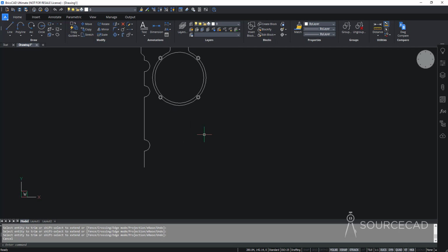So once again, I'll start with a construction line, and I'll go to the line tool and I'll maybe select this center. And I'll just add a single straight line of approximate length. It should be just long enough. It should be longer than this line at least. So that's what the idea here is. So now with that, I'll go to offset, and I'll first start with an offset distance of 8. Enter, and I'll make an offset of this on the left side and on the right side.